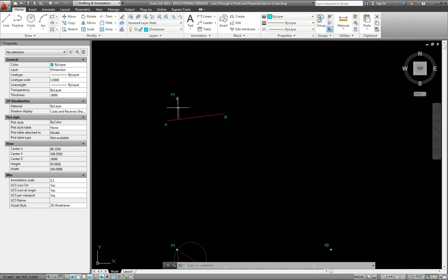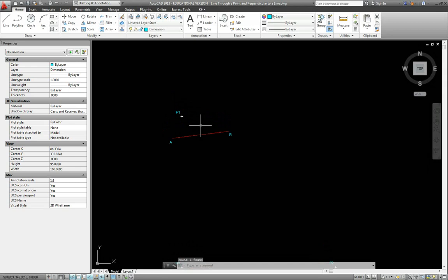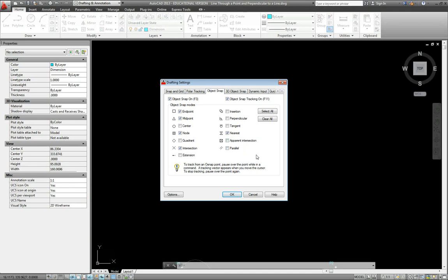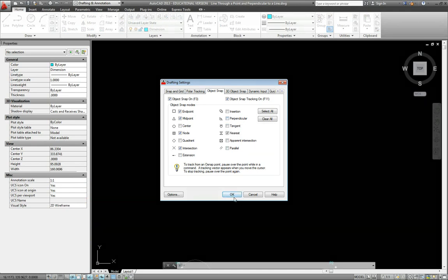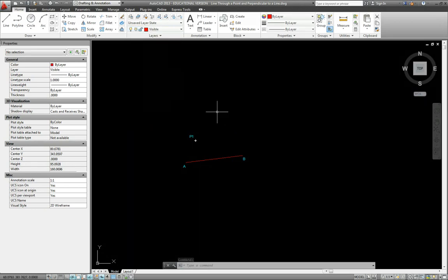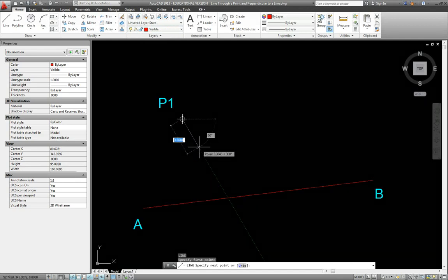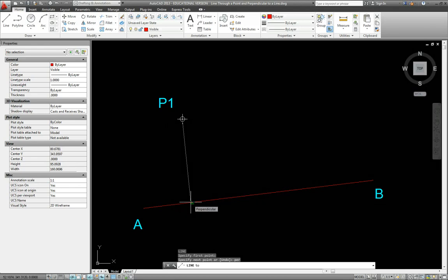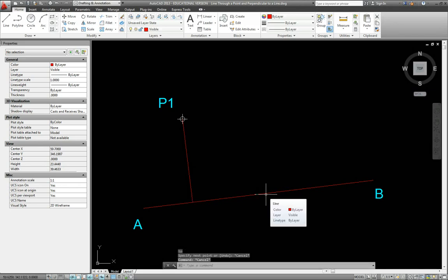If you were faced with the same situation in AutoCAD, what you would want to do is use the perpendicular object snap. You can turn that on as a running object snap, and that is here, or you can do the one-time override. I want to demonstrate that again. If I switch to my visible layer and enter the line command, start off at this point, and then do the one-time override, PER, enter, the only object snap it's looking for now is the perpendicular snap. Once you see that snap, you can left click, and there is your perpendicular line.